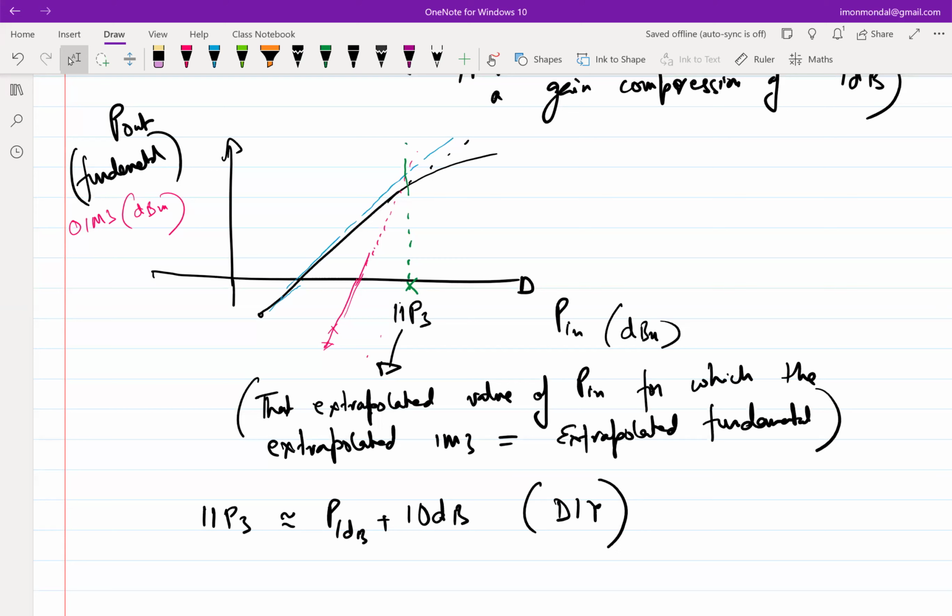One of the reasons that it may not be a big issue is if you are using a differential circuit. I'm not sure whether 613 has probably covered this. If you use a fully differential circuit, then the second order distortion gets suppressed, right? It gets cancelled, so it is not dominant anymore. If there is a mismatch, then sure, there will be some. But in general, it is not dominant, so you can neglect it.